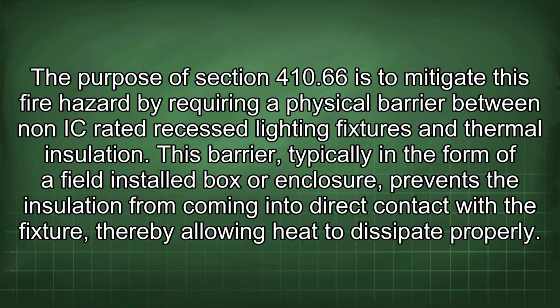The purpose of Section 410.66 is to mitigate this fire hazard by requiring a physical barrier between non-IC rated recessed lighting fixtures and thermal insulation. This barrier, typically in the form of a field-installed box or enclosure, prevents the insulation from coming into direct contact with the fixture, thereby allowing heat to dissipate properly.